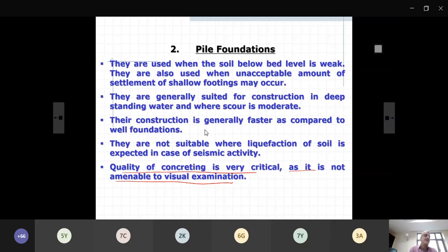Segregation, proper mixing, you don't require hardly any compaction if it is pumpable. So if you can pump a concrete, it gives you an indirect assurance that your concrete is of good quality. In fact, I am of the view we should ban other than pump concrete for bridges.